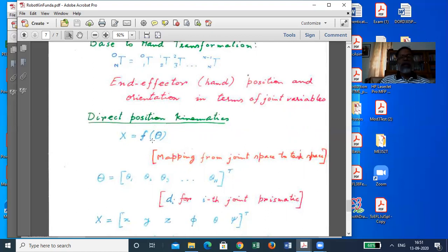But before we come to that, let us see an example. And that example is important because even in planar case, many students, many people try to do all these paraphernalia of 4x4 homogeneous transformation matrices and so on. In planar case, all the rotation axes are along the z direction, so a lot of matrices are unnecessarily handled, and that can be handled easily through plane geometry.